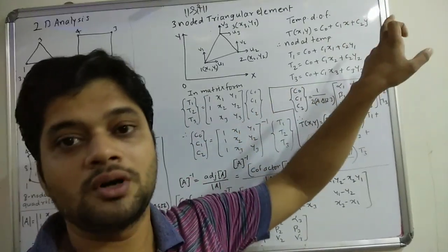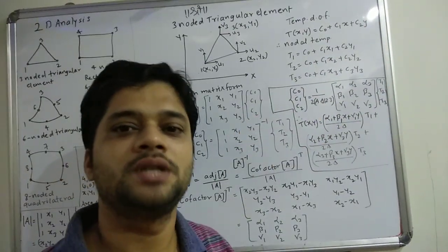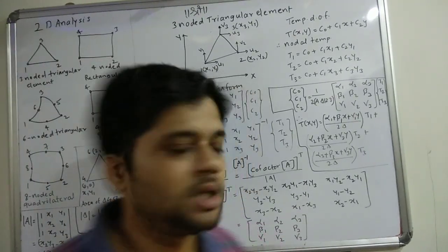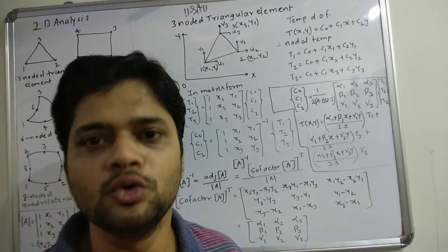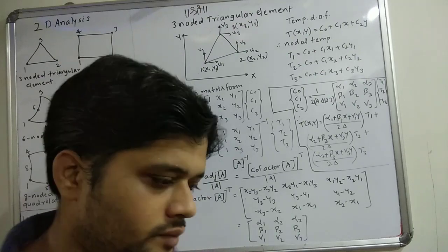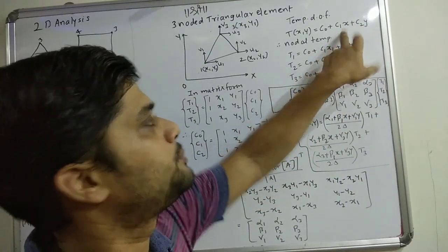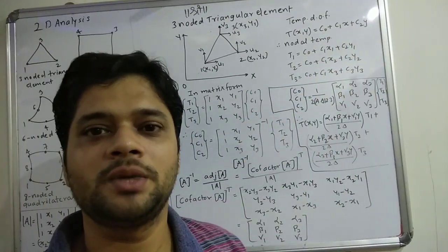If we have to write a quadratic approximate function, then it is c0 plus c1x plus c2x square, and so on. At that time we had some other rules which we followed in order to derive the differential equation. But as far as the approximate function is concerned, this is still a linear approximate function, but it is in 2 dimensions.